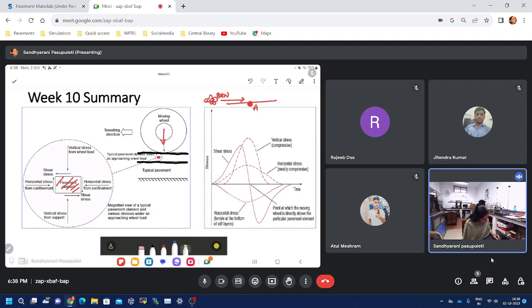Now our element is here. This red color point is our element. The blue color is the car, which is very far now, so you can see the stress is 0. As the vehicle keeps coming, stresses will start increasing, which is what you are seeing. After some time the vehicle has come and been placed over that element. That means there is a lot of load on that element, so the element has to use its entire strength to resist that load. The stresses would be maximum at that point.